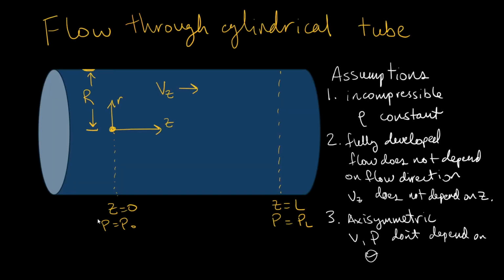So that first equation again was dp dz is equal to c0. We can solve this with separation of variables, so dp is equal to c0 dz. If we integrate this, we can think about our boundary conditions for this problem. So if we return to that original page, our boundary conditions are shown right here. So at z equals 0, our pressure is equal to p0.